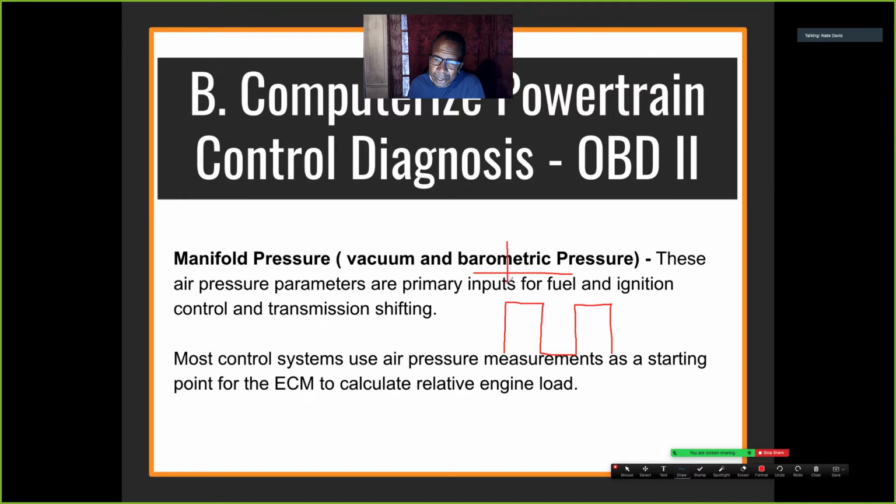This is one event. And let's say that this is supposed to be 159 hertz. Right now I'm just talking about barrel. That's key on engine off. I want to see 159 hertz for the atmospheric pressure. That's where your initial pulse width is going to start from for the injectors. That's your altitude. If this wasn't at 159, was at 85 hertz,